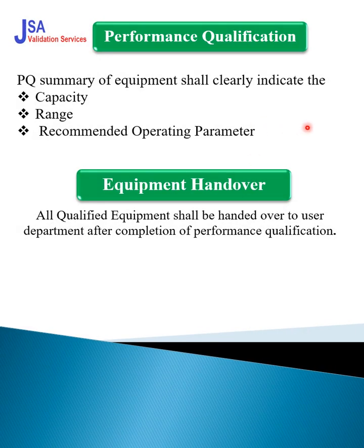After performance qualification or requalification, we have to mention the capacity range and recommended operating parameters of the compressed air system, and then the equipment handover. After the qualification of the equipment, if it is suitable for routine or commercial use, we can hand over the system to the end user. So this is all about the performance qualification and requalification of compressed air.